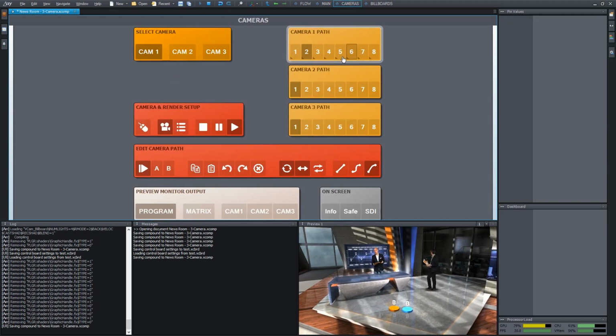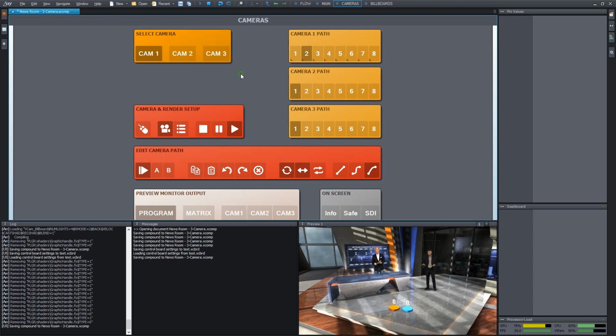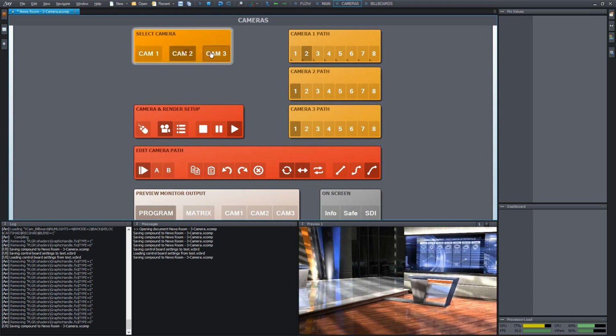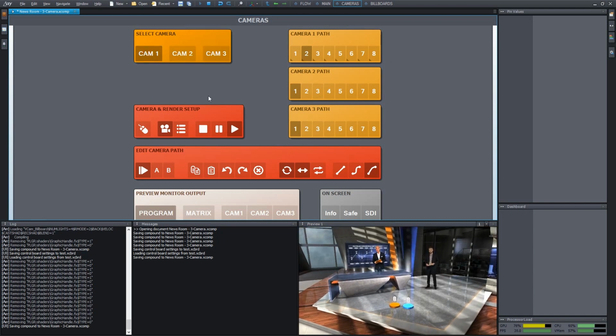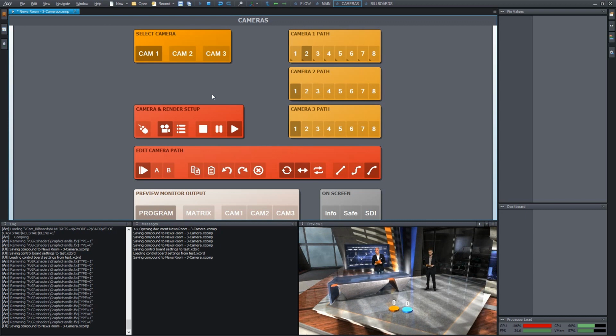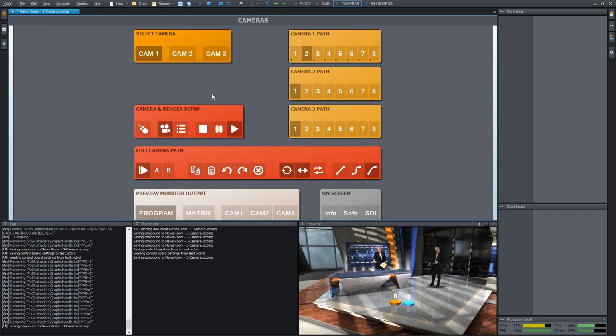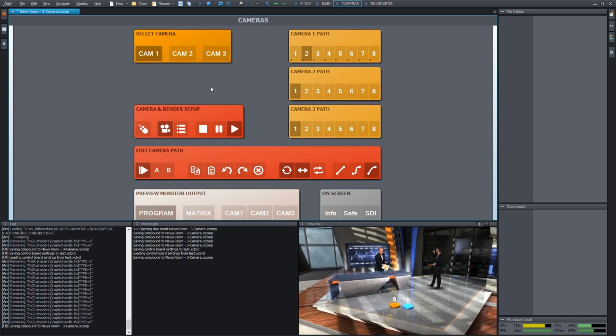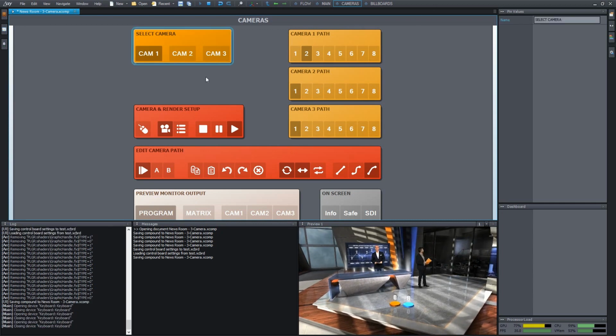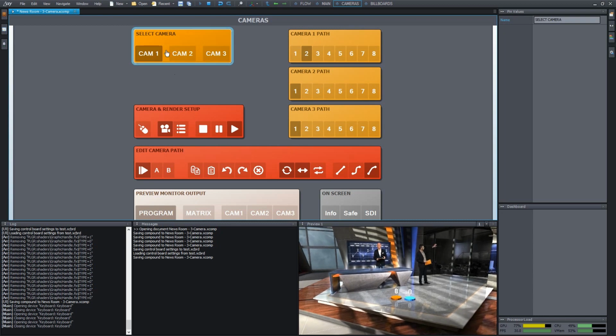So far, we have performed all control functions by clicking on various buttons and icons. This may not be particularly convenient during live conditions. For this reason, it is possible to allocate these buttons and switches to various external control devices. The most common one is the keyboard attached to this PC. Let us try and associate the 3 camera buttons to the 1, 2, and 3 keys respectively on the keyboard.